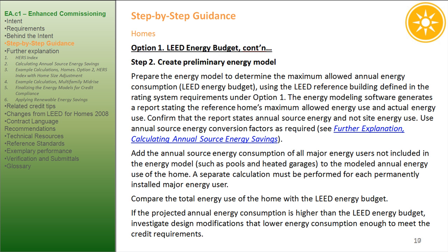The energy modeling software generates a report stating the reference home's maximum allowed energy use and actual energy use. Confirm that the report states annual source energy and not site energy use. Use annual source energy conversion factors as required. See further explanation, calculating annual source energy savings.